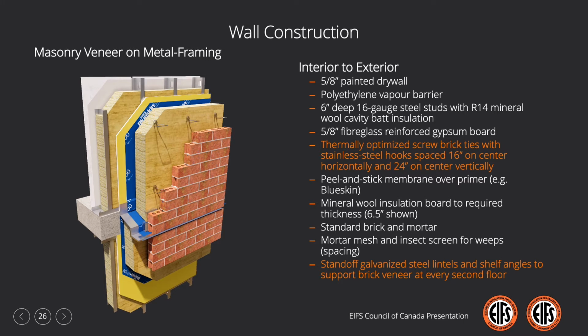While the construction's been optimized with regard to thermal performance, some constructability challenges did emerge, specifically with regard to structural integrity. With the exception of the Montreal assembly, the exterior insulation requirement translates to the face of the veneer being some 11.5 to 16 inches outboard of the supporting structure. This led RDH to make the following comment in the report. Few brick tie options are currently available to accommodate CI thicknesses for Vancouver, Calgary, Toronto, or the high R wall cases. These walls may not be structurally feasible.